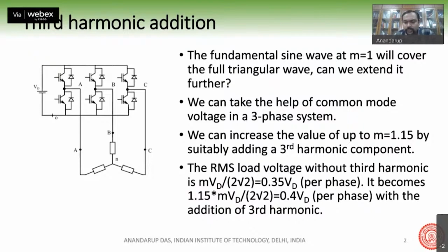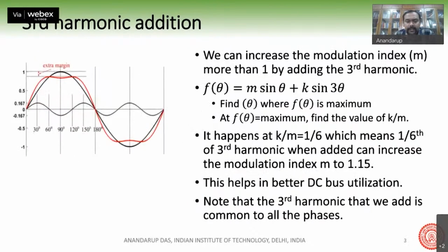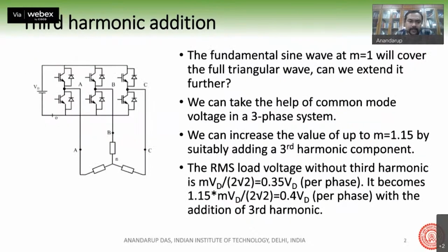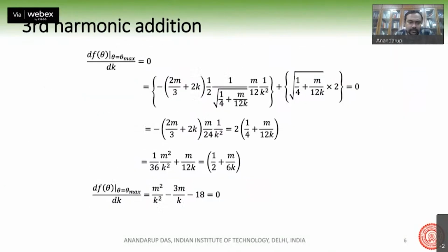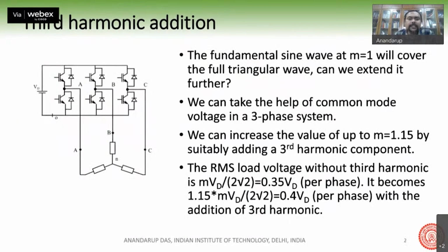The equivalent circuit is not shown here, but basically it shows that there is a controllable voltage source, and that controllable voltage source is producing a fundamental as well as a third harmonic. The third harmonic voltage exists in the pole voltage, because you can think of that switch getting replaced by one controllable voltage source, which is generating a third harmonic.